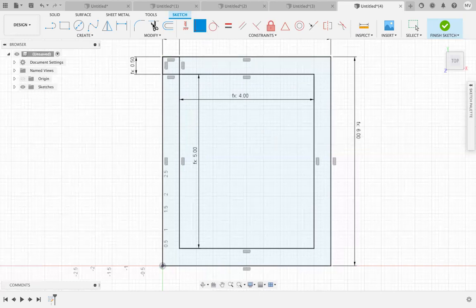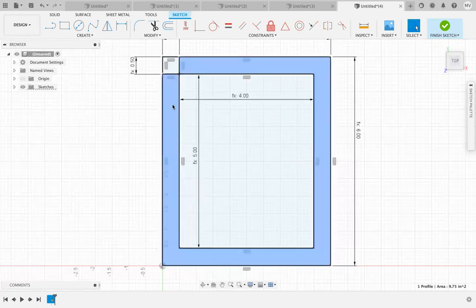Okay. Now there's a few things I want to clean up. Like this square in the corner is not really part of my design. I don't want it there, right? I want this blue wall, top edge of my box, to be one shape. These lines were just meant to help me place this inner rectangle, but they shouldn't be dividing up my sketch. So if I click on one of those, I can just type X and it turned it into a dotted line. Now that dotted line is not dividing up my shapes.